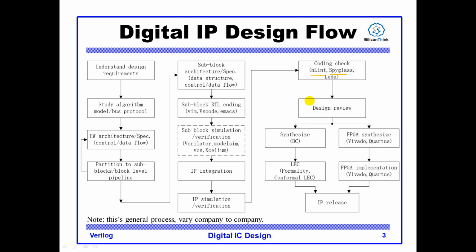After that, we usually have a design review. The owner of the function block will call for a conference and invite some engineers in your group to review your design. I think this is an important step. In this step, we will double check whether you have understood the algorithm and the bus protocol correctly, and we will check whether your hardware architecture is reasonable, and there may be some advice to improve your hardware architecture.